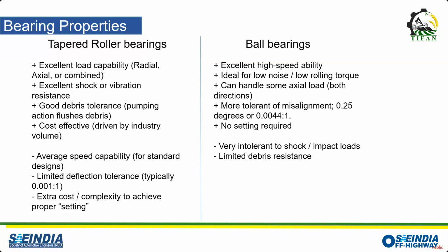So the first thing you need to consider is the load, and then the second thing is other parameters, like what is your cost aspect, what is your system doing, right? Whether you need a constant system or an open system, how you are going to use the bearing, whether it is on a shaft which has tight tolerance or loose tolerance, right? So you check all those things, but most likely we would like to go for ball bearings. It is up to your design, what your design is telling you to go ahead with, right?